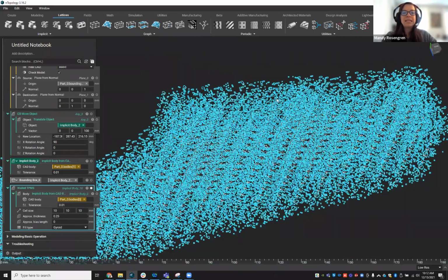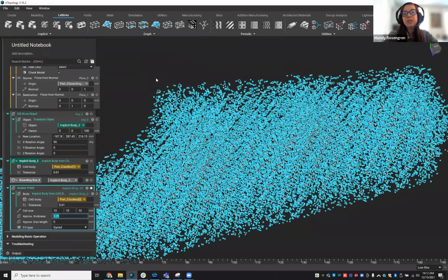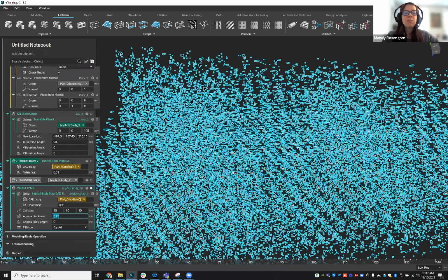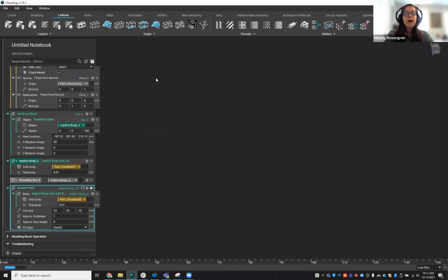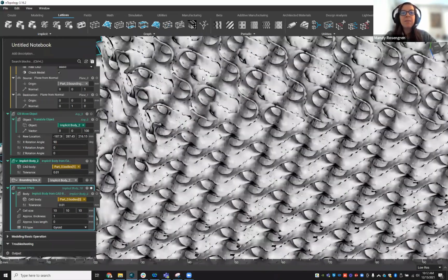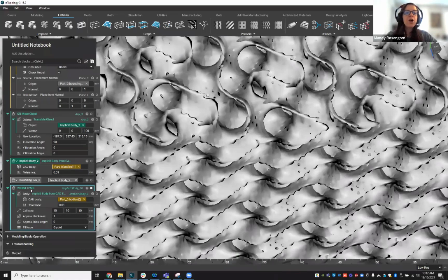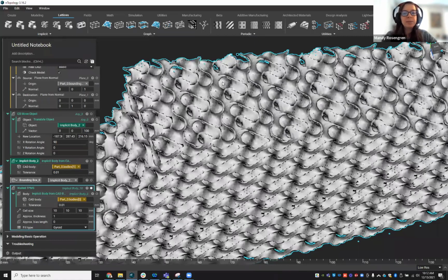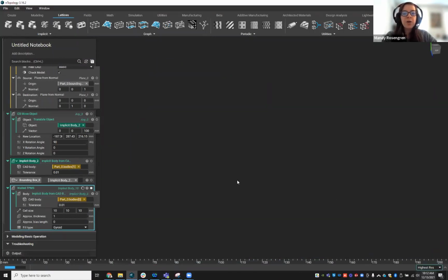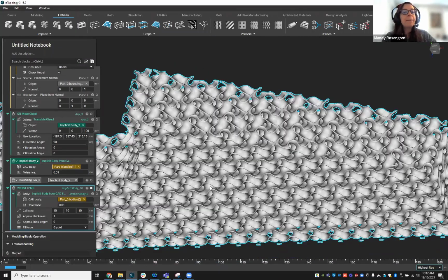and we have that approximate thickness, it looks even more difficult to see because we have such a large cell size and small thickness in this low resolution. That doesn't mean our part has a problem. I'm just increasing this to 1 millimeter, and we still see some of these interesting triangles. One way to double check that your part looks as you expect is to switch from low to a higher resolution. Already we can see this is looking a lot better.